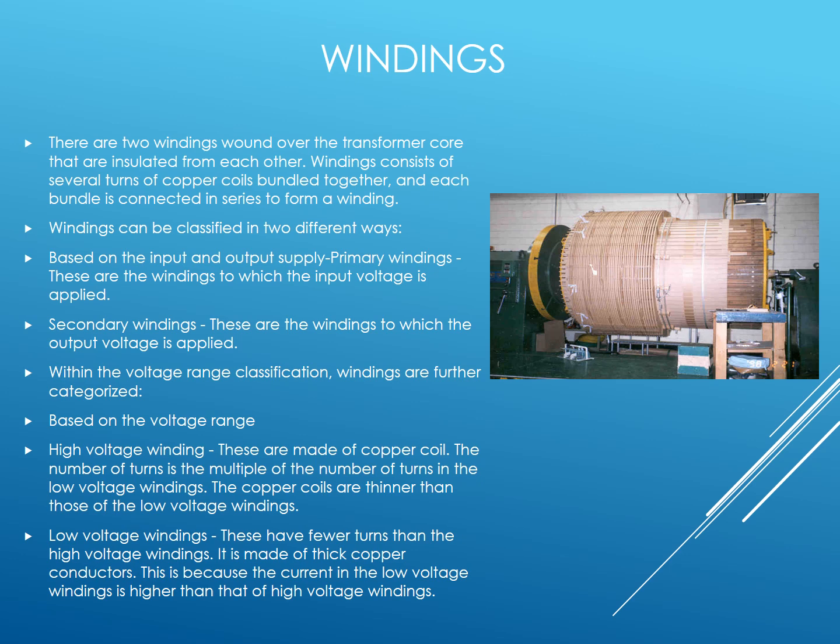In sandwich type, each high voltage portion lies between two low voltage portions to reduce the leakage flux. Sandwich type is used in shell type of transformers.